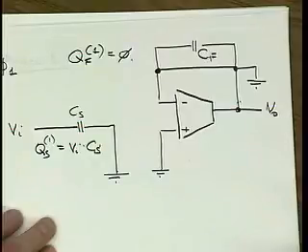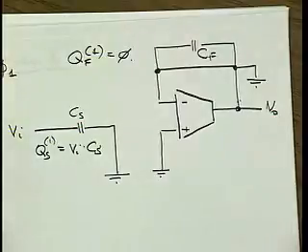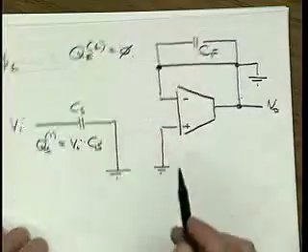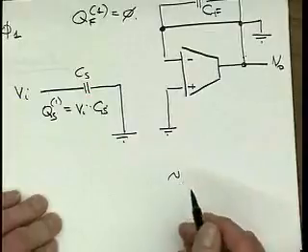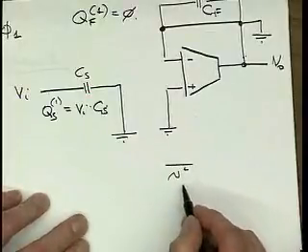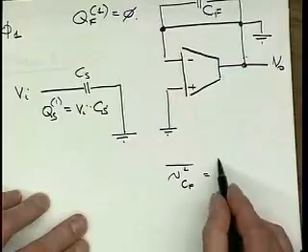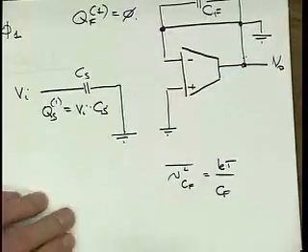What happens if I give you a capacitor and tell you to go and discharge it? Can you do that? If you just use a wire and short circuit it and then open it again, what's the voltage that's stored on the capacitor at the end? Yeah, kT on C. So in reality, the V squared that's stored on CF is equal to kT on CF, right?